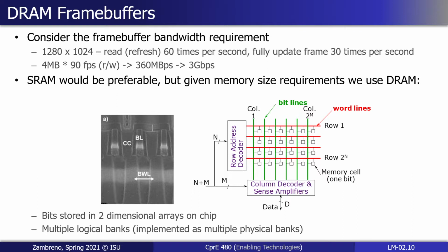But now I'm telling you that actually, in reality, that does then correspond ultimately to some row and column layout in memory. But this row and column layout of our DRAM doesn't correspond at all to the resolution of our screen. This is a physical layout of the memory on the chip. And we don't generally have to know what that two-dimensional layout is on our chip. And you can think of it also as having a third dimension. If this is describing a single bank of our DRAM memory, our DIMMs, the devices we actually purchase and put in our workstations, would have multiple of those individual logic banks there. So it's almost a three-dimensional layout in that sense.